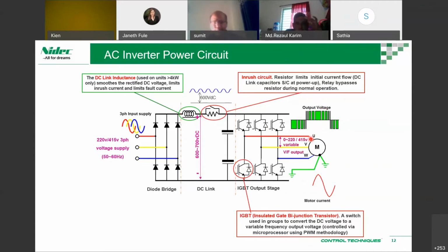But this depends on the condition of the VFD. Let's say if it's a repaired drive or so, then you may need to test even further with the motor and so on. Okay, so for this output voltage, when you connect the motor, you get a sinusoidal current like this. Of course, there will be spikes and so on. We'll do that later.